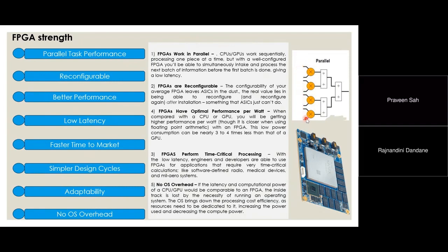So you see, if I have to implement this, first these are getting multiplied here, adding, and then again the output of this is getting added. If I use an MCU, a microcontroller is nothing but it processes the instructions sequentially. So if I say to process this task it takes 5 nanoseconds for this, 5 nanoseconds for this. So an FPGA can do this activity like multiplication, addition in 15 nanoseconds only.